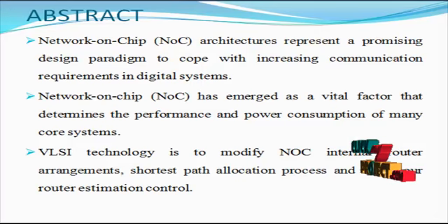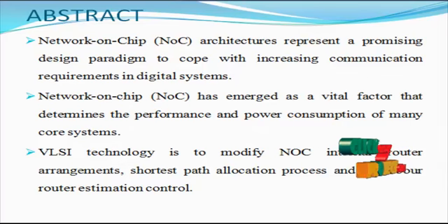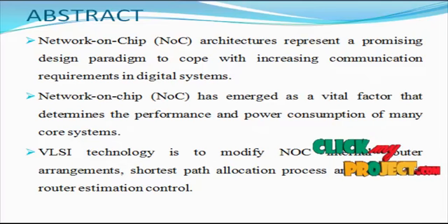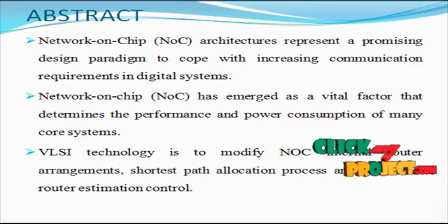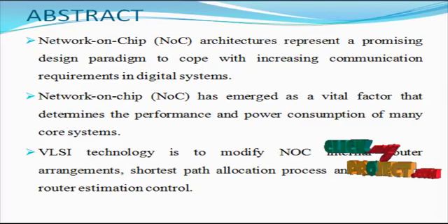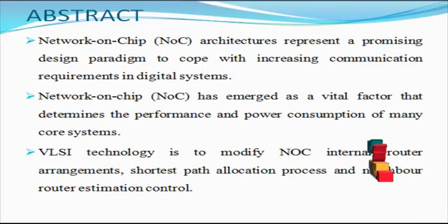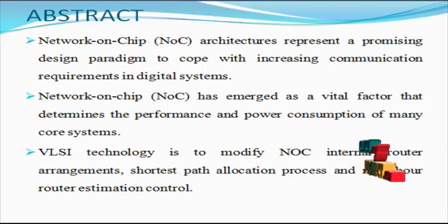With the scaling of 3D IC technology development, 3D system design is becoming the main research trend, especially network on chip as a novel option for integrated multi-core systems, which is submerged in the 3D tide. 3D NoC can make use of many advantages of current 3D IC, including reduced global wires, decreased end-to-end delay, lower power, increased package density and saved chip area, and supporting interconnect design with different CMOS combined in manufacturing technology.